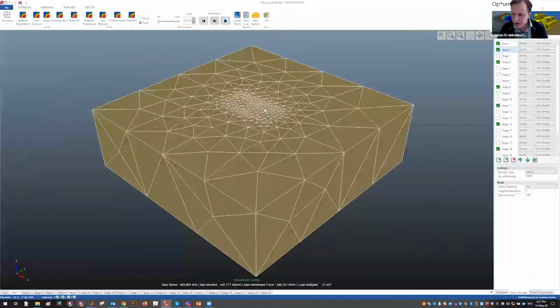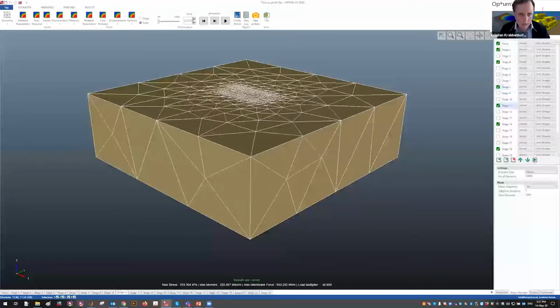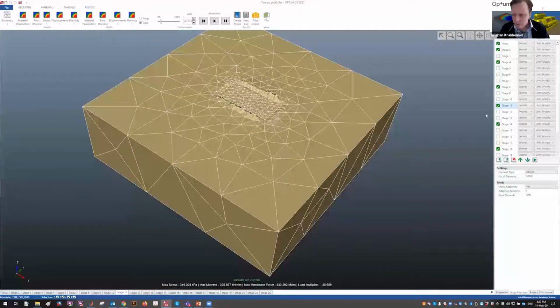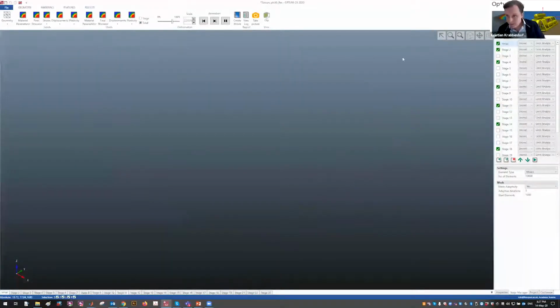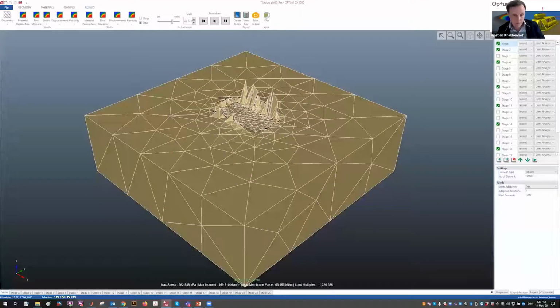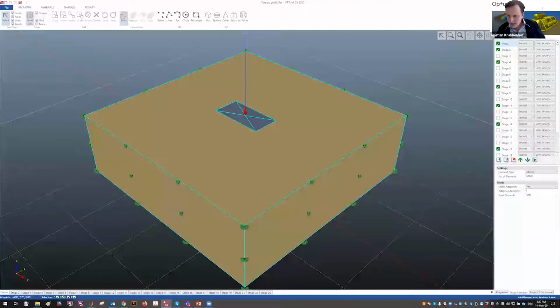You see that when you go in the diagram and get close to this left edge here, torsion becomes more dominant, and that's of course how it should be. Good. So you can do that, and I did it. I found the maximum V, and then I manually put the fixed 756 and whatever down to 0, and that can be done, and it's not too tedious to do.